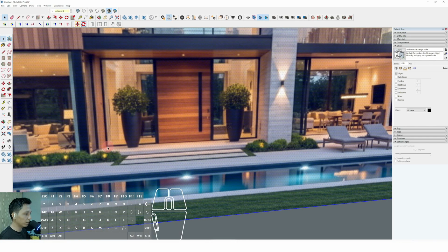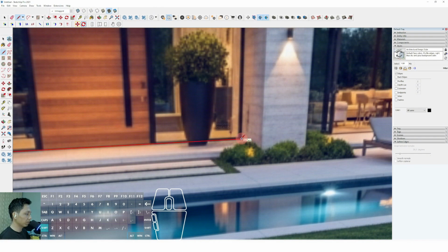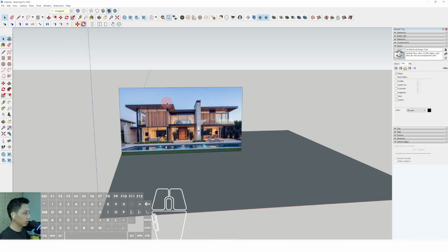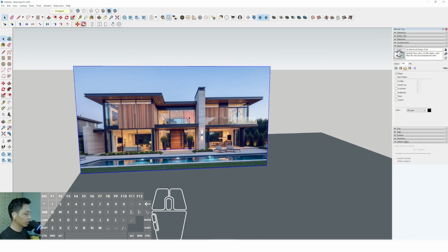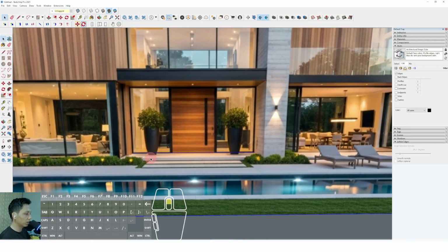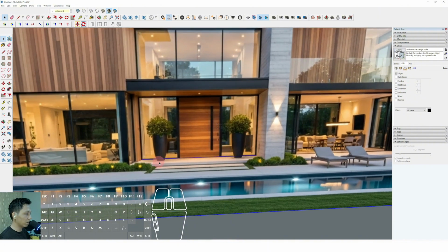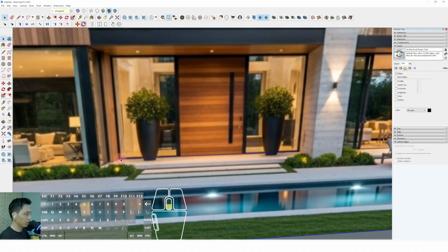Okay, then we can draw the line from this point until this point. We can draw using the line tool, create the point in here and finish at this point. Now we can select all, with the image and also the line in here, right click and make a group. Then I suggest this center area is around 4.5 meter, from this point until this point.